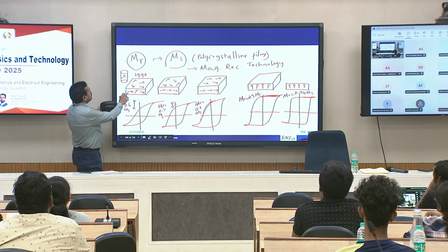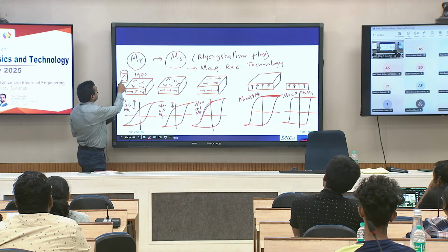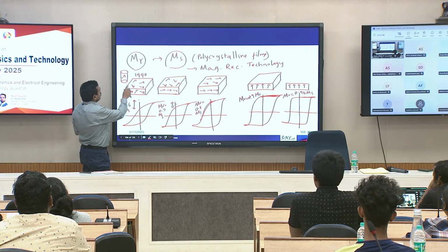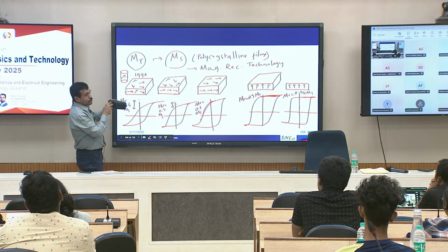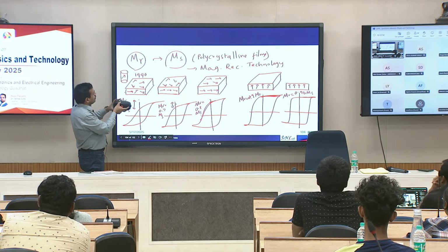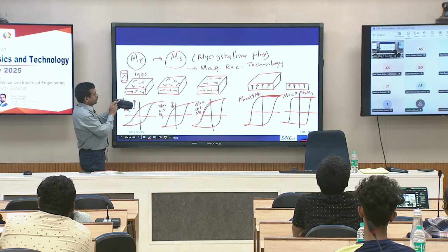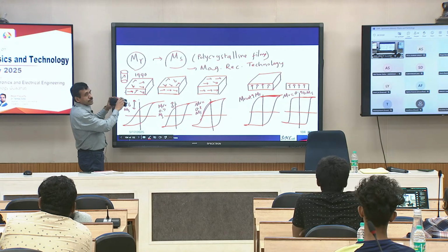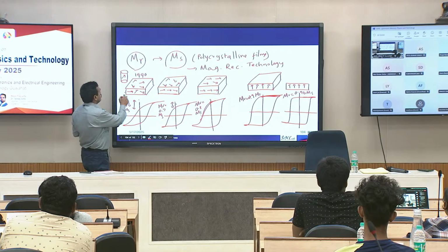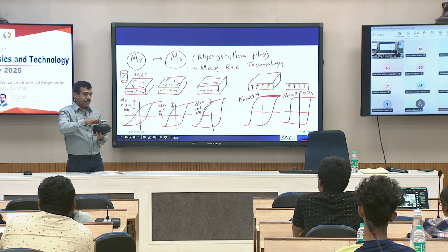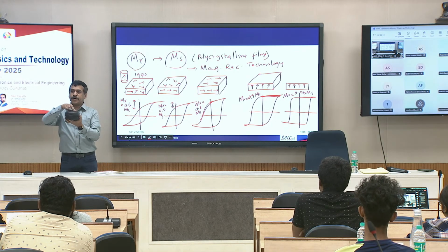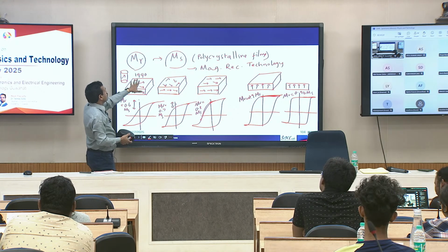So, in longitudinal magnetic recording, your grains may have an easy direction that, viewed from this perspective, is completely parallel to this plane, or tilted at some angle with respect to this plane. So, magnetization can be this way or like this. A few possibilities exist. And now, if you view from the top, within the plane, again the magnetization can point towards you, or towards this wall, or towards this wall. It can point towards many directions, right. So, from the top also you have randomness.